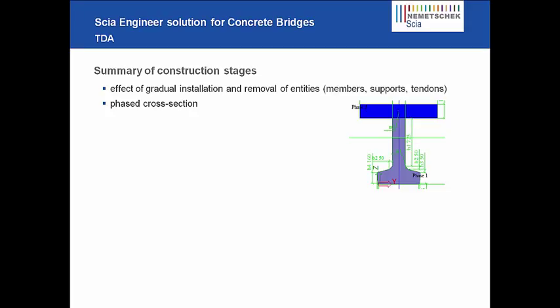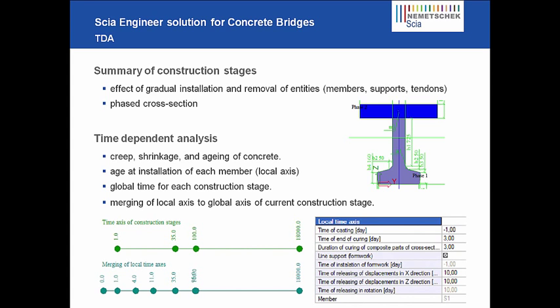You can also take this into account by modeling the prefabricated beam as a single beam and the plate that will be added later on as part of the section that will be added later on. This type of section can also be taken into account in the analysis, in the construction stages.